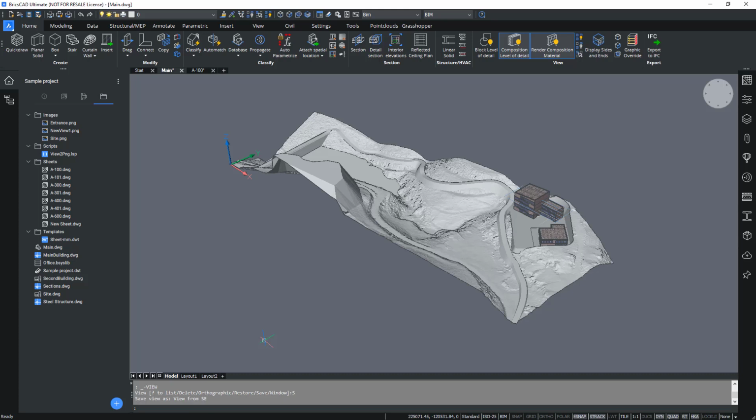Hit Enter to confirm. Now go on to Files and expand the script folder. You should find the view2png.lisp file present. This script is shipped with BricsCAD V22 and it's designed to export a screenshot of your saved views from your model file. Those images will be in PNG format and will be named based on your view names and saved in an automatically created folder called Images.